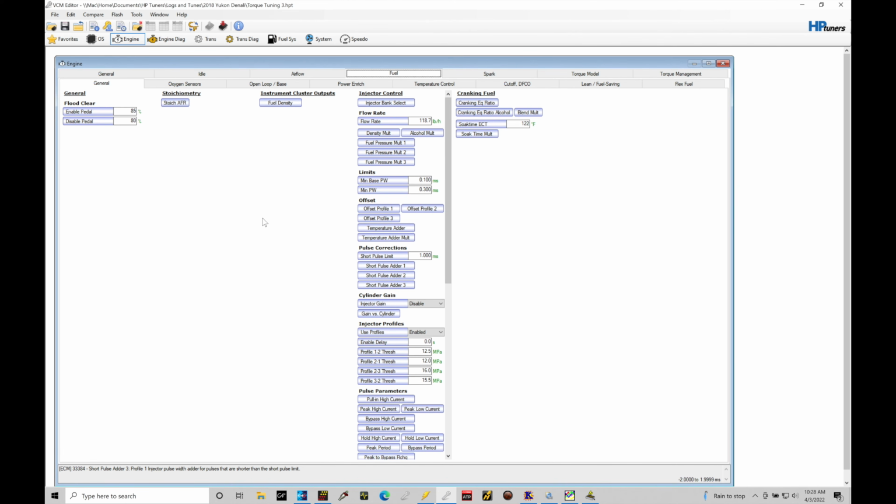Now, the biggest thing here, because the Gen 5s are torque based, and we know that everything relies heavily on accurate air mass reporting, from the cylinder air mass being a scaling factor into our spark tables, into our variable cam control tables, as well as any of the torque modeling, if we start to skew the air mass side of things. So say we're spraying that water meth, or we're spraying the secondary fuel through port injectors in addition to the direct injection, and all of a sudden we run rich.